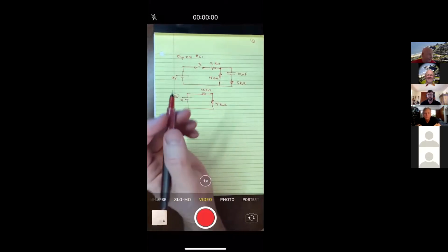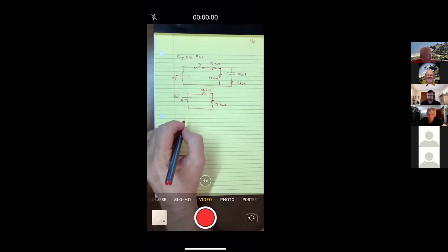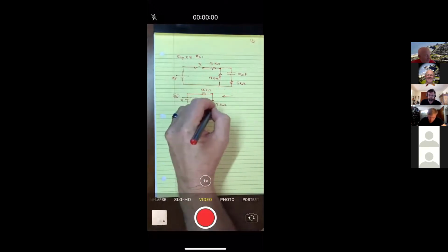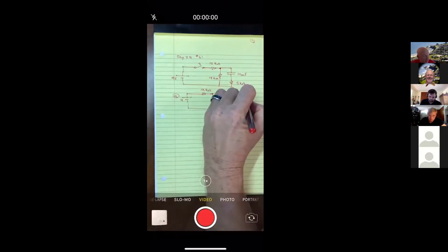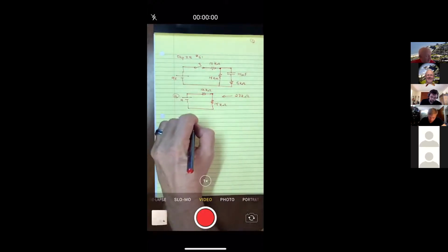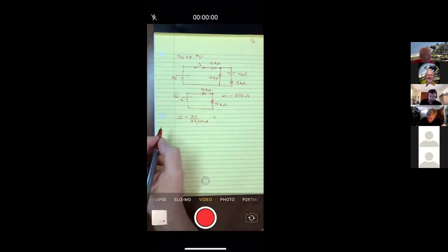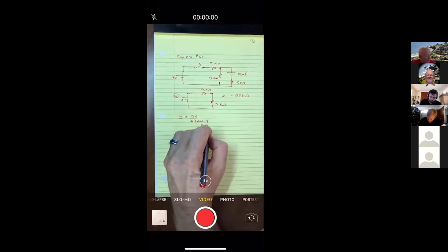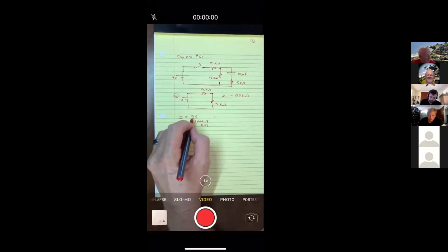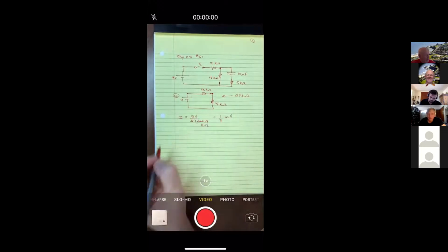Okay. So, all right. So this could be written then as the equivalent is 27 kilo ohms. So the current would be the same in each of them. And it would be Ohm's law, 9 volts divided by 27,000 ohms. Actually, I'll show you a little trick. It's kind of nice to write that as kilo because 9 over 27 is 1/3 and 1 over a kilo is a milli. So this is 1/3 of a milliamp.